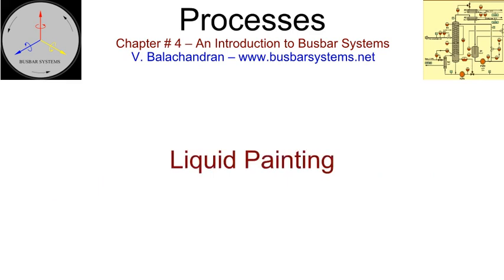Liquid painting. The liquid painting was extensively used before the advent of powder coating. After the surface preparation, moisture is completely removed before undertaking further processing. This is best achieved in an oven. A surfacer is applied for providing additional protection. A primer coat is applied with a spray gun to the surface, which forms the interface between the paint and the surface. Putty is applied for covering minor undulations, deformities, and dents that may have occurred during the manufacturing process.